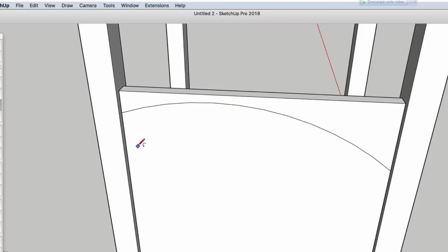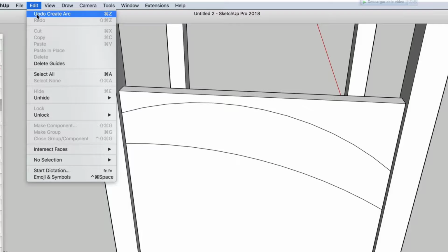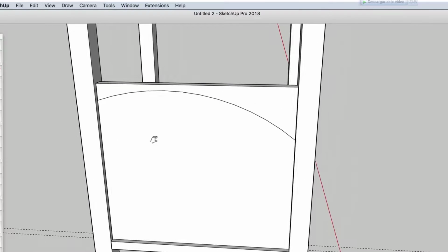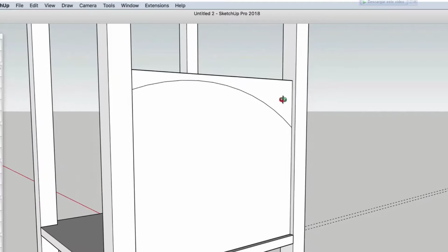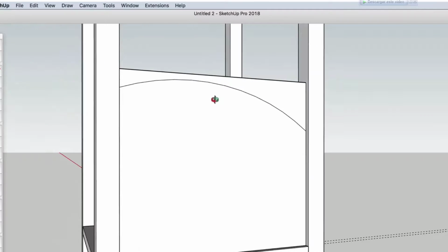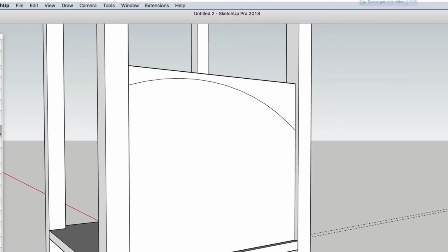Do be careful as you draw. SketchUp may try to infer to the pillar edge, so be sure you are drawing on our new rectangle only. With this new arc drawn, we can cut this top shape away with push-pull. Push this surface until it meets the back surface. A good way to be sure is to look for the on-surface inference. It will be a blue rectangle inference.